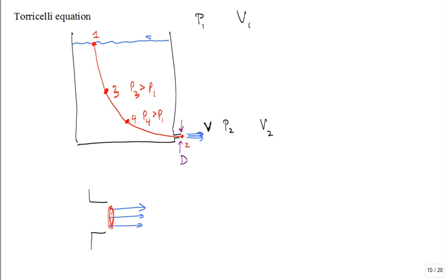And the streamlines of that water are shooting parallel to each other. They're not curved. And later we'll talk about Euler's equation and how to calculate fluid pressure changes in a bend. But they're straight lines, infinite radius of curvature. The pressure doesn't change from some location going from the edge to the middle of that stream of fluid shooting out.